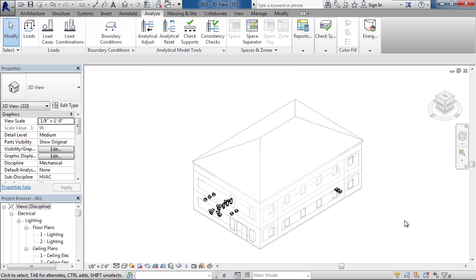So as a review in this lesson, we looked at the energy analysis energy settings. We first started talking about the requirement of having a login to Autodesk 360 in order for the analysis to run because those compute in the cloud now. Secondly, we talked about where the energy analysis settings are located on the Analysis tab and in the Energy dropdown section. And lastly, we went through the variety of different energy analysis settings on the Energy Analysis window, including export settings as well.